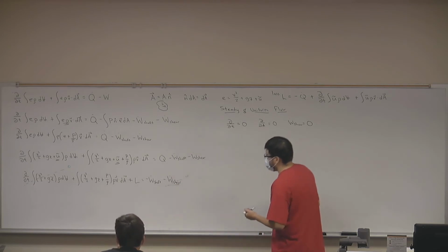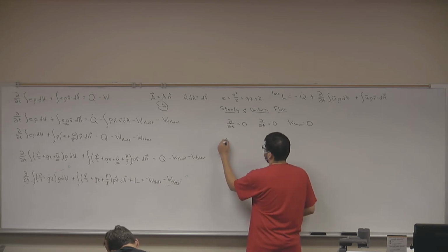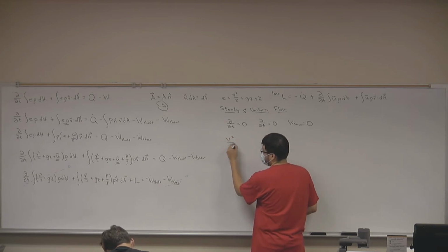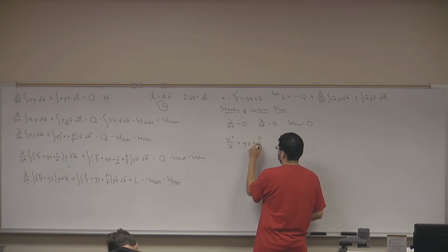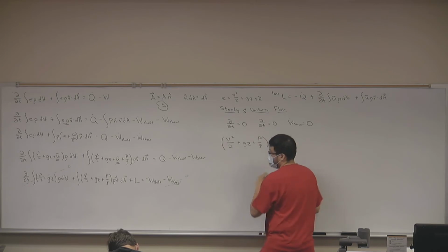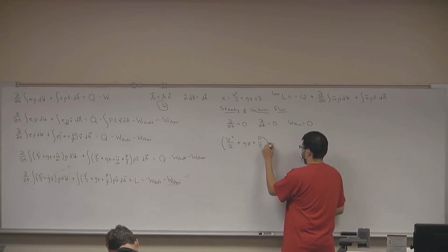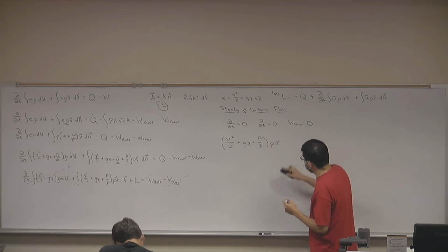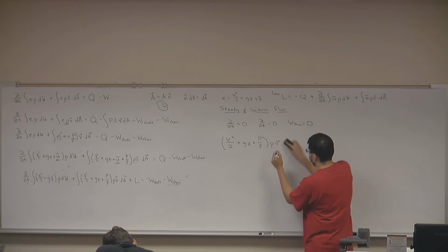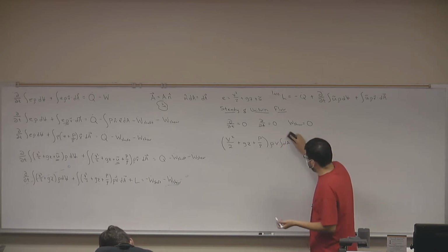So what I end up with is my flux, and my flux corresponds to my specific energy multiplied by density, velocity, and area. And again, if you don't remember where this is coming from, remember that we have density, we have velocity, and then we have integral of dA, which is just the area of my control surface.